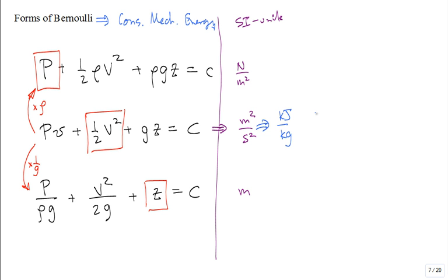And a kilojoule is energy, and a kilogram is mass. So we can interpret that middle equation as energy per unit mass. The mechanical forms of energy per unit mass are being conserved along that streamline, steady flow, inviscid, incompressible, blah, blah, blah, right? Well, look at this one above. How do I make that look like an energy per something?